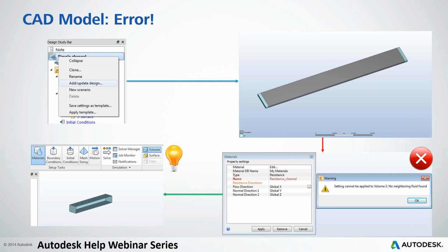To figure out that pressure drop, you've got 1/2 rho v squared, so you need to grab the fluid density to calculate what the pressure drop is going to be, and then the software is looking to calculate it from nodes that are outside of the resistance material. The other thing that you gain by adding those caps, you want to have them just far enough that your boundary condition isn't touching volume that's doing math for you.